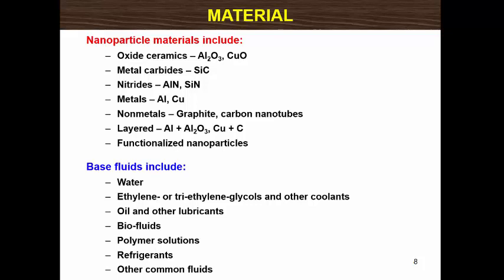In summary, by adding nanoparticles to conventional heat transfer fluids, a new generation of heat transfer fluids was generated, which is called nanofluids. Nanofluids have some potential benefits such as high specific area and therefore more heat transfer surface between particles and fluids, high dispersion stability, reduced pumping power as compared to pure liquids to achieve equivalent heat transfer intensification, reduced particle clogging as compared to conventional slurries, and adjustable properties including thermal conductivity and surface wettability by varying particle concentration to suit different applications.